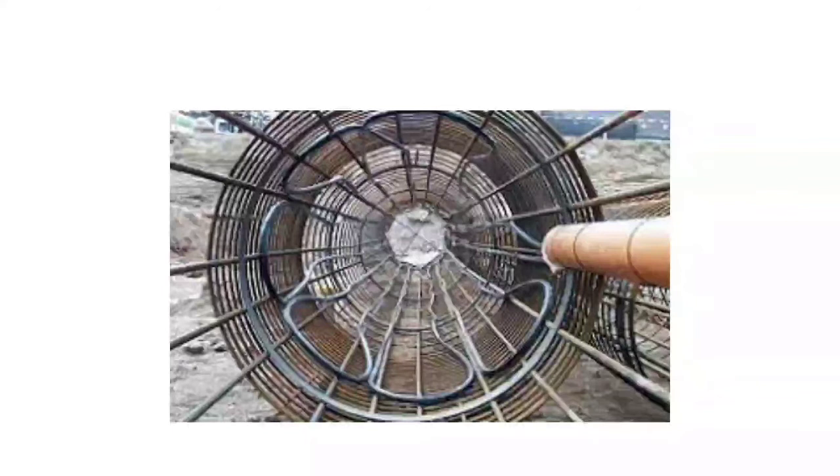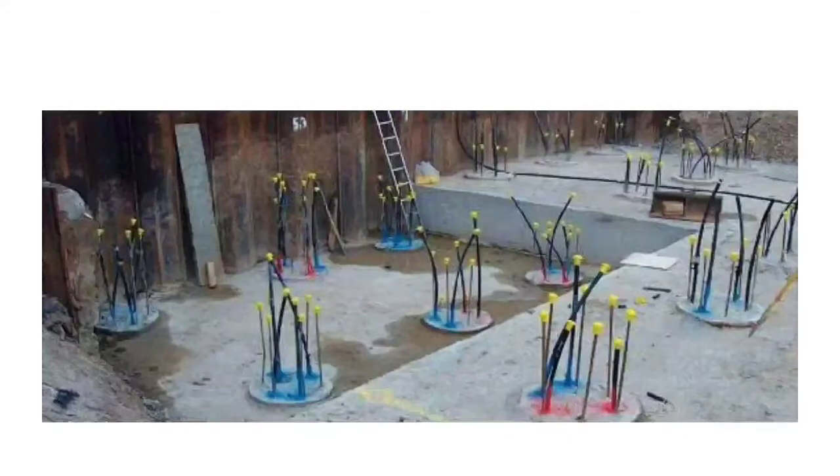Once it is filled with the heat exchange fluid, it will be pressurized and locked, alright, and then the concrete will be poured into the hole. Once the concrete is poured and has hardened, we will reapply the pressure. So this is how the end will look. That is, the pipes are coming out and locked outside.